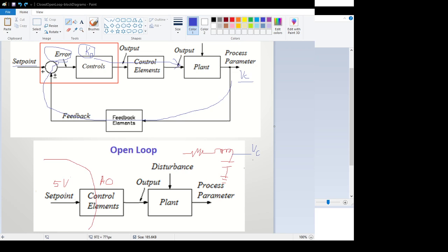And I've got channel 0 enabled, my input is enabled, and it's allowed to fluctuate between -10 to +10 volts using a 5 hertz filter and engineering units. I also have my output enabled, -10 to +10 volts, engineering units. And that's enabled there also. So that's my analog card. I'm using channel 0 and channel 1.